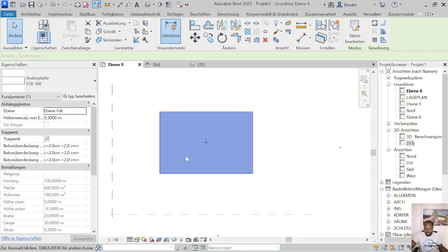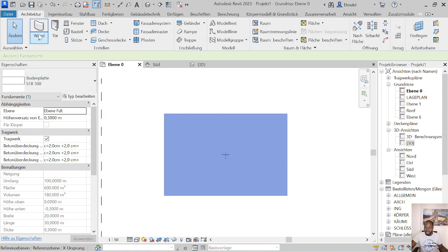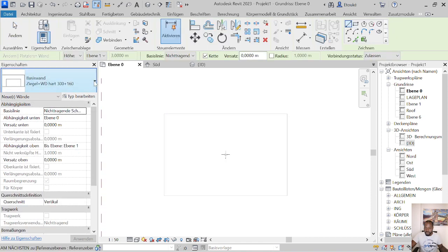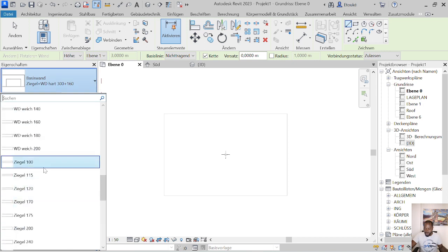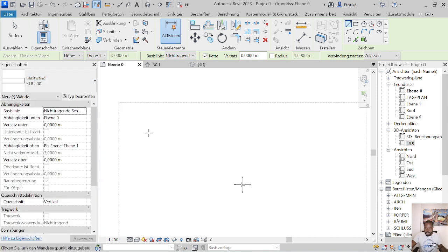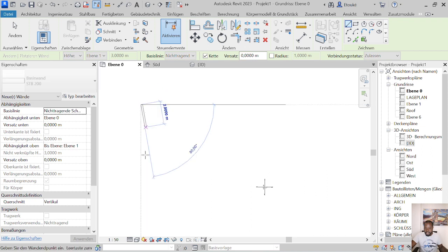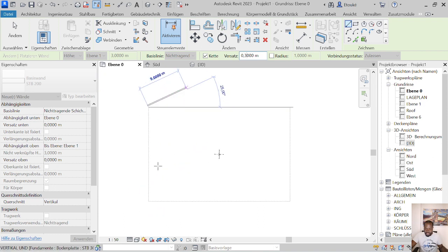So we go back here, we go back, and now we will start to design the walls. So we will go back to architect, and choose the walls. Which kind of walls do we want to use? So we will use concrete 200, and we can start. We can give here, okay, we want it like 0.3 meter inside. So now we can start.